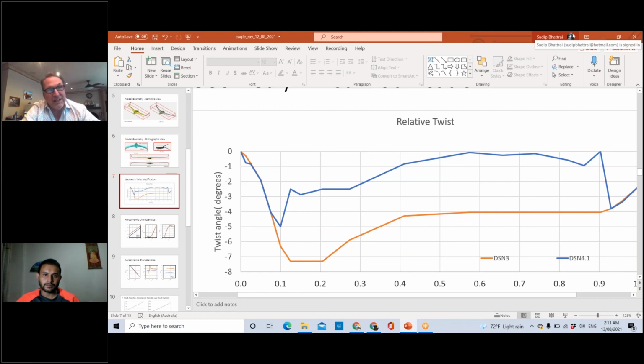Now the washout, I take that back, excuse me. I'm saying it backwards. The extra washout should help it trim. So it'll bring the elevons down. So you should be fine. You'll have to probably put some trailing edge down elevons in to retrim it,